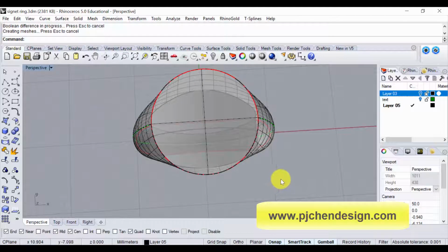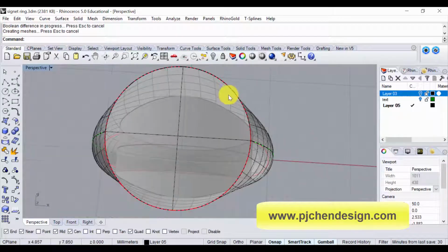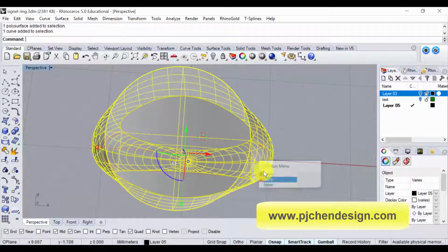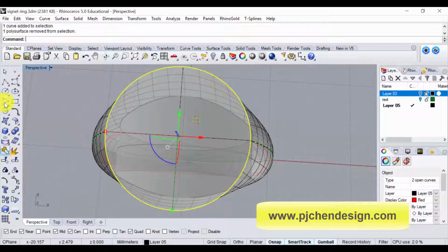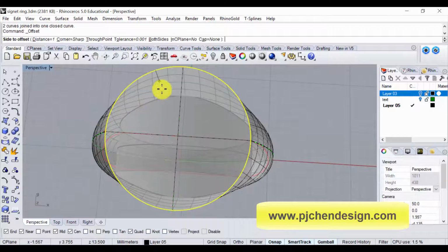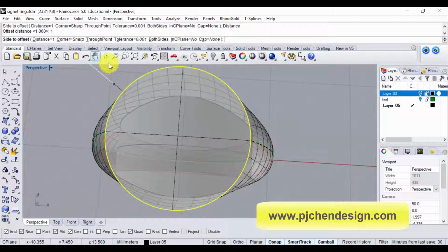All right. Next, we have this curve, we just cut it in half, and I'm going to join it back together. I'm going to give a wall, a little distance from the text to the wall. So I'm going to offset this outside the original curve that I have, and approximately the distance is 1 here, so you can type 1, and then by moving the mouse inside and outside, you kind of see there's a little bar there.